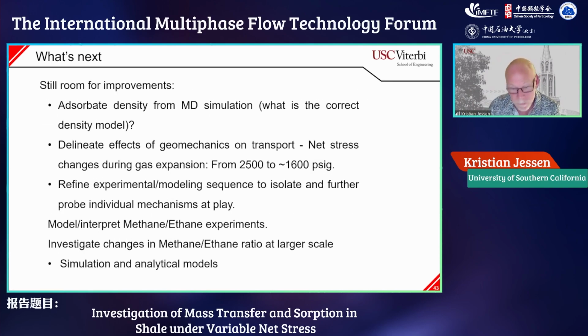What is next? Well, the top of my wish list is somebody comes up with a way of figuring out what the adsorbed phase density is. People are getting better and better at molecular dynamics simulation to try to understand these things. The key challenge remains, though, that the materials we're working with are made by nature over time and are not nice, homogeneous materials when it comes to surface chemistry. So when it comes to understanding adsorbed phase density, there's still a lot of work to be done. And while many molecular dynamics people like to have relatively simple structures, that definitely has to be extended to more heterogeneous structures to try to understand and develop adsorbed phase density models for continuum scale observation.